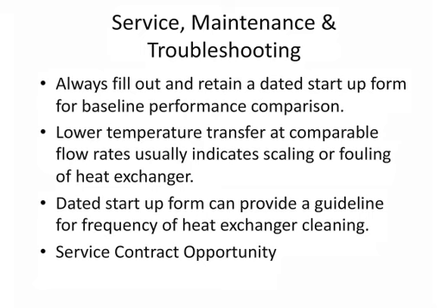And that should be the reference point, because when you do that with a freshly installed heat exchanger that's clean from the factory, when you come back later to do the same kind of performance check, as you see that temperature transfer being less, several degrees less, well, that's your clue that it's probably starting to foul the heat exchanger. It may be time to service it. It also will help you gauge the frequency that needs to occur. So again, always perform that on startup. It's also, for you service contractors, a service contract opportunity if you think about it.